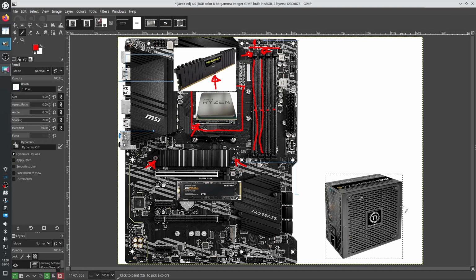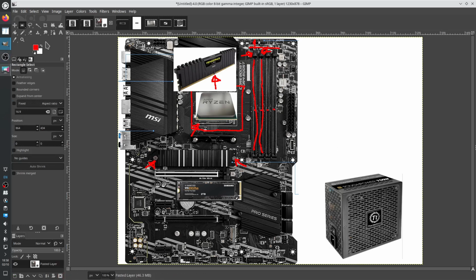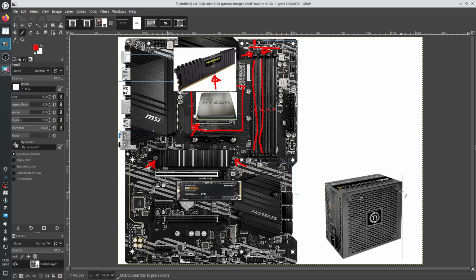So you need to connect the big connector. So the big connector is this guy, the main connector of the motherboard. It's called ATX. Okay. The second place that you connect is this 4 or 8 additional motherboard power.